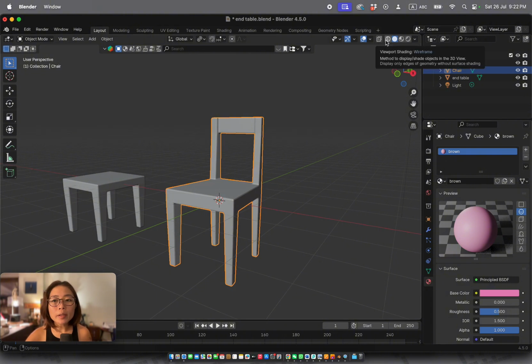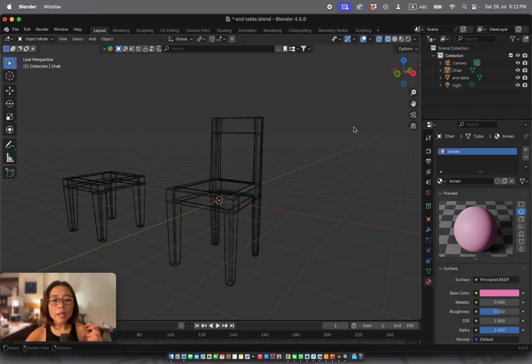And the first one is called wireframe. When we check wireframe, we will get rid of all the gray shading on the meshes, and we will see instead a lot of lines. These are showing all the edges you have created in the scene. By default, the wireframe mode will have the X-ray on also.